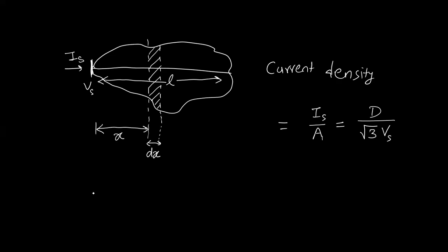Yeah. So the voltage drop in this small area is basically the impedance of that feeder section. Let us assume Z is the impedance per kilometer, and if you multiply that by the feeder section length, which is dx, that gives us the total impedance of that feeder section, Z dx.